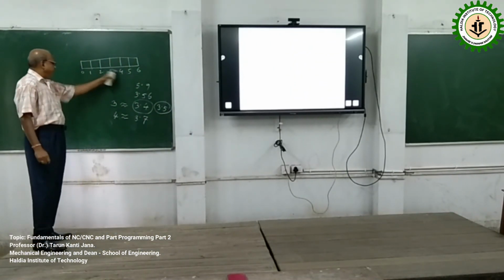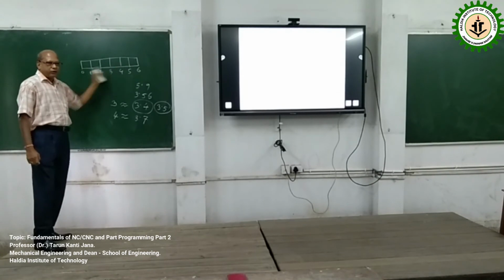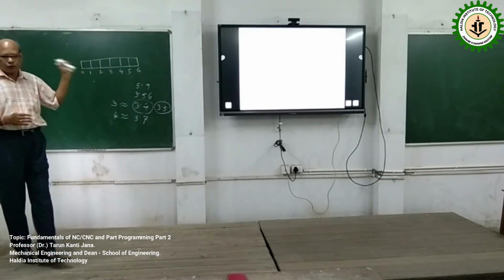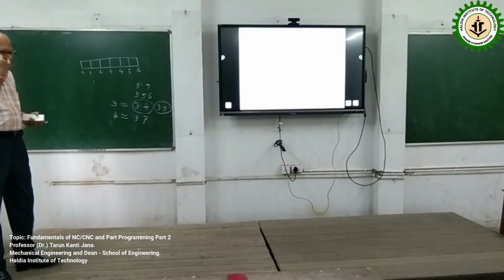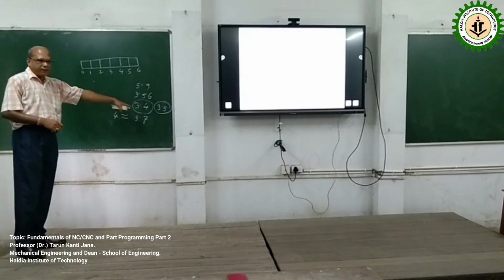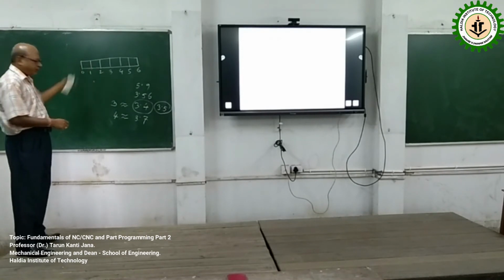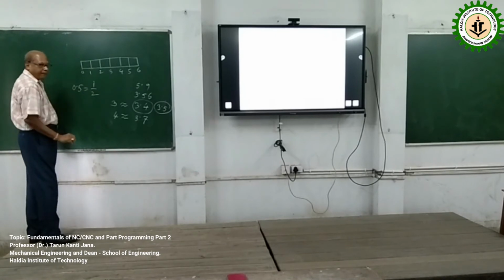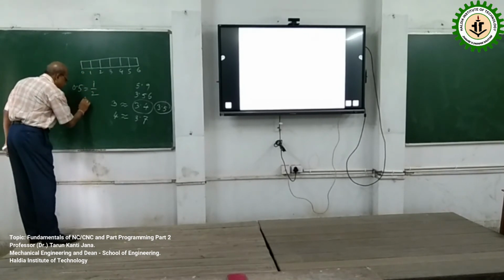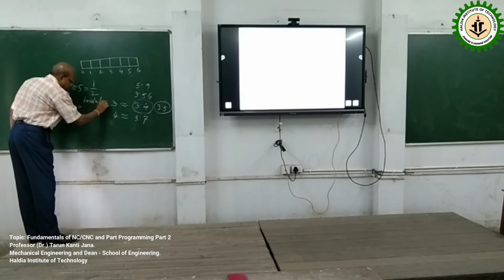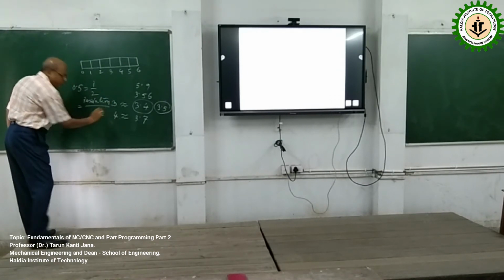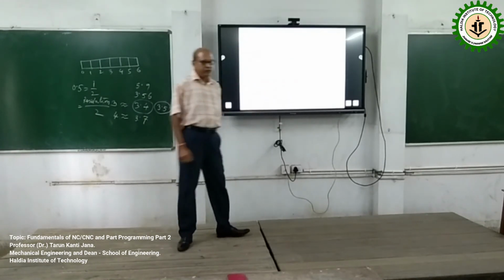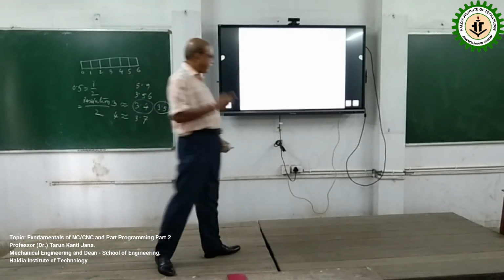in this particular scale, 1, 2, 3, 4, the resolution is 1. Any fraction part is not shown, there is no such calculation. So if 0.5 is your maximum error, in terms of resolution, 0.5 is how much? Basically half of the resolution, which is 1. So that is what controls resolution. This is one part of error.